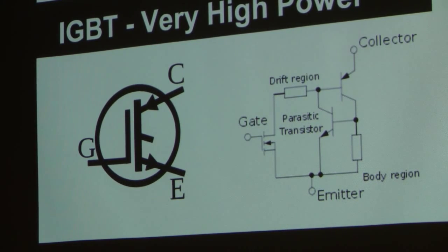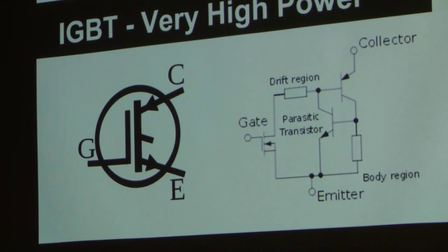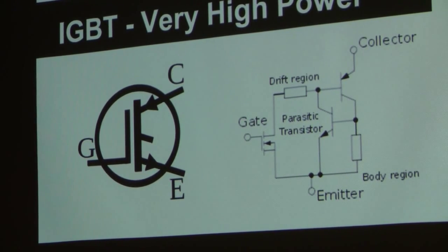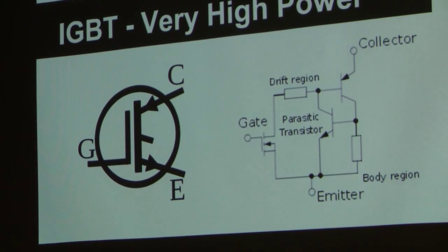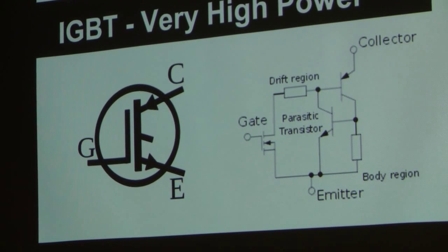Most of the people I've read about using them successfully recommend knowing your stuff when you're doing the gate drive, or using a gate driver. I've never used them personally because every time I start to, I keep coming back to wanting lower passive dissipation in my device with a lower voltage drop across it, so I end up coming back to a MOSFET.